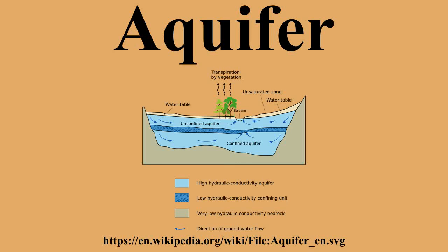For salinity control in such a case, annually an amount of drainage water is to be discharged from the aquifer by means of a subsurface drainage system and disposed of through a safe outlet. The drainage system may be horizontal or vertical. To estimate the drainage requirement, the use of a groundwater model with an agro-hydrosalinity component may be instrumental, e.g. SAHYSMOD.